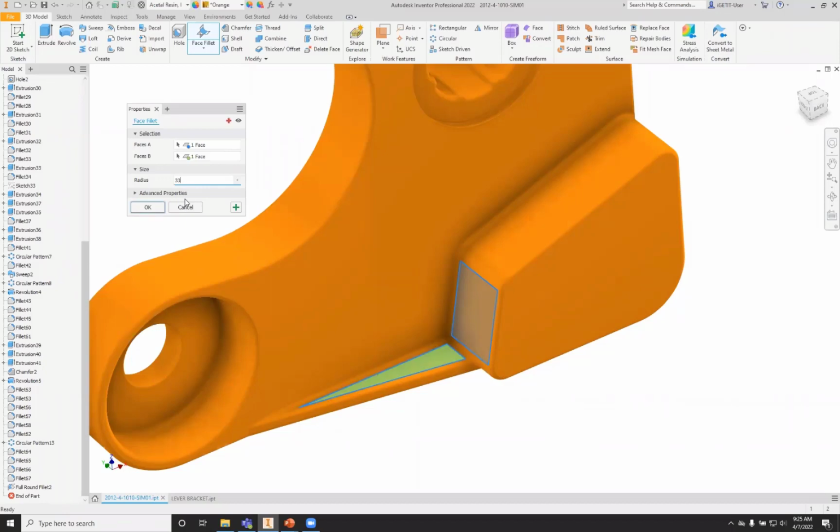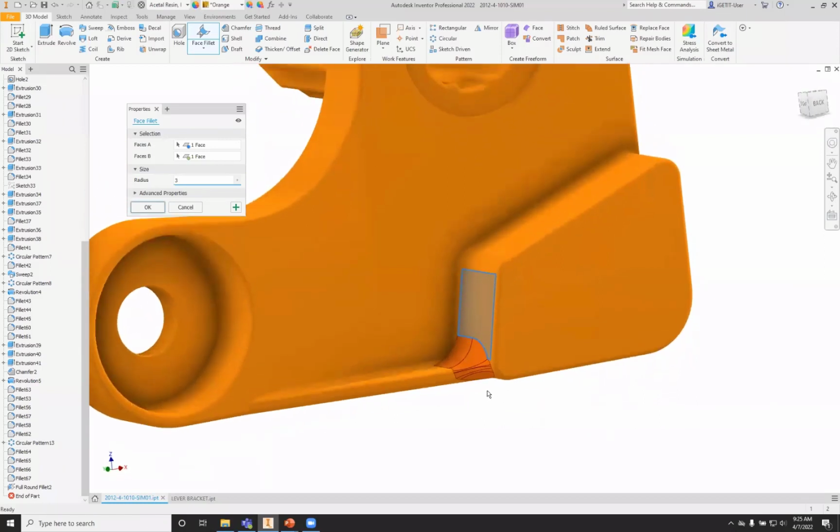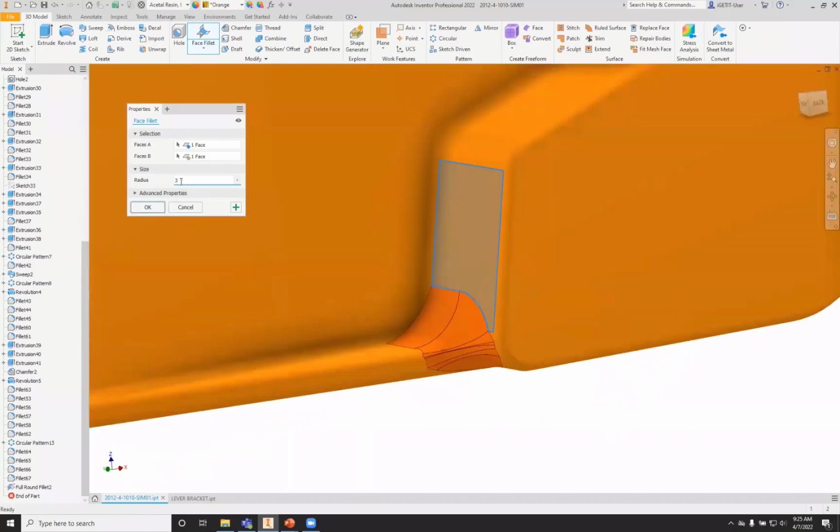And again, another good example there. You'll notice, if we try to create a fillet here that's too large, that can't be computed, we get a little red X up here, basically giving us a preview error, but also indicating that this is something that can't be computed. So we'll take this back to 3 millimeters. So here's our preview for what that new fillet will be. And any of these other fillets basically get removed. It kind of ignores them and just creates that blend between any of these tangent edges and faces.